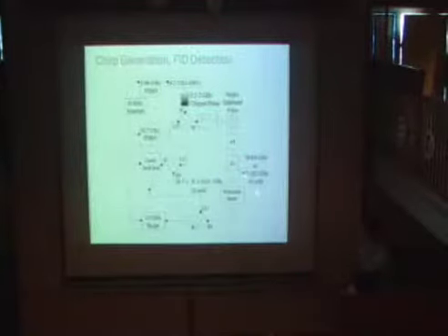So then we let its pulse interact with the molecules in the vacuum chamber, and use another gain horn to detect the chirp pulse and free induction decay, and mix this free induction decay with a 75 gigahertz GaN oscillator to down convert the frequency below 12 gigahertz, and read it with a fast oscilloscope. To make sure that we can average the signal in the time domain without significant phase drift, we use a 10 megahertz standard oscillator to lock all the frequency generation and detection.